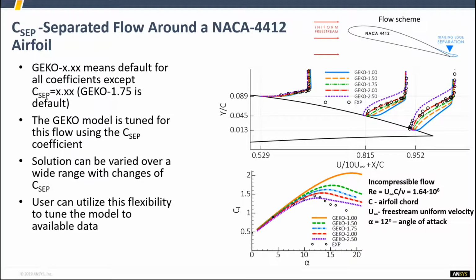So when you want to change the wing and put the wing in different configurations, you can do a lot more in CFD because you've tuned your turbulence model to suit. You can see what we're looking at here: the trailing edge of the wing where the flow separates. When the flow is aligned with the wall, it's going to be coming up from the wall directly.